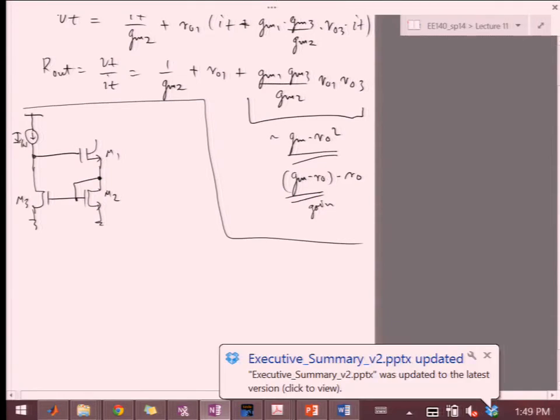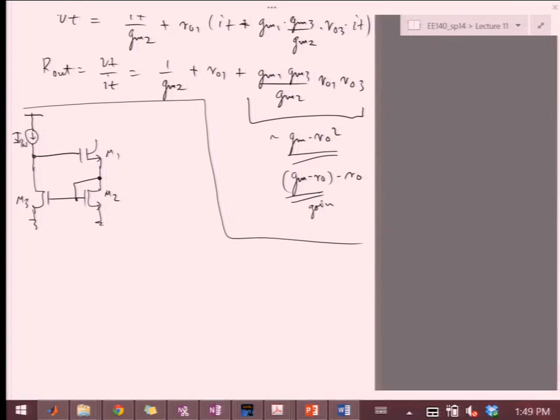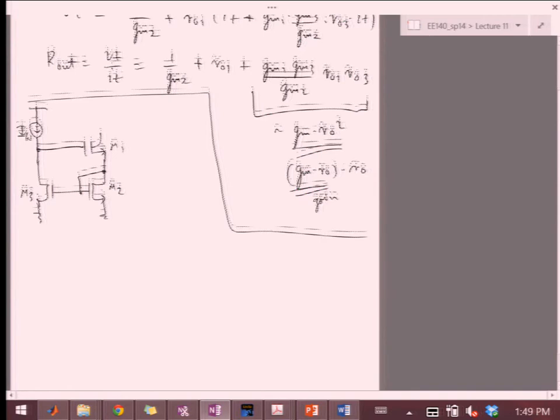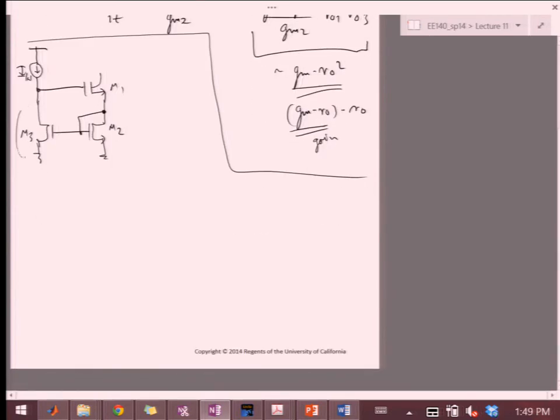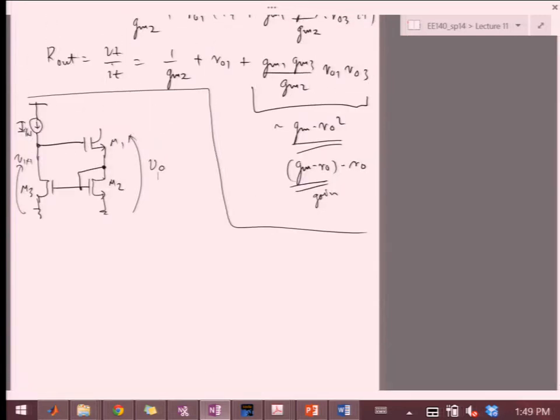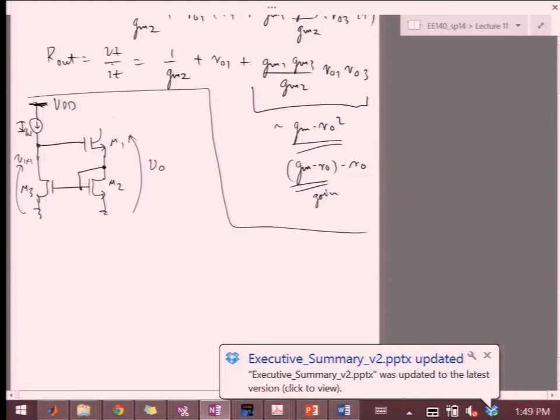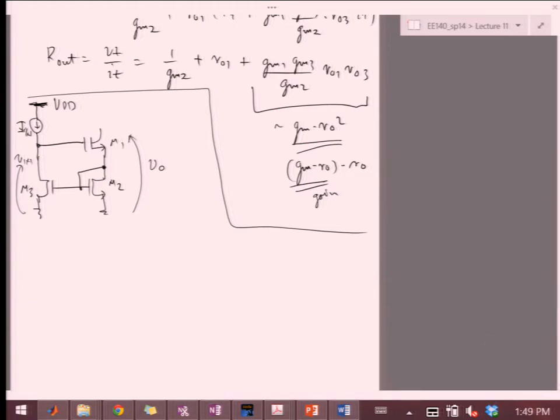Another thing, so this is small signal stuff, but one thing that's interesting to us is also how low can the input V in here and the output voltage, how low can these go? And the reason is that, especially in modern processes, I have a finite supply, a finite difference between this, which is, let's say, VDD, and ground. And I want to be able, especially over here, to put a lot of different circuitry.